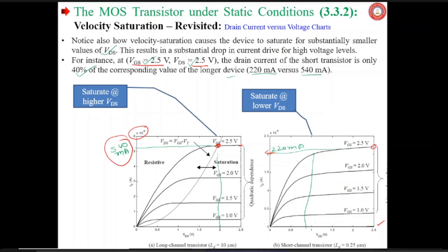If you consider the PMOSFET, it will be the same. All the derived equations hold for the PMOS transistor as well. The only difference is that for PMOS devices, the polarities of all voltages and currents are reversed. This is illustrated in this figure, which plots the ID-VDS characteristic of a minimum size PMOS transistor.